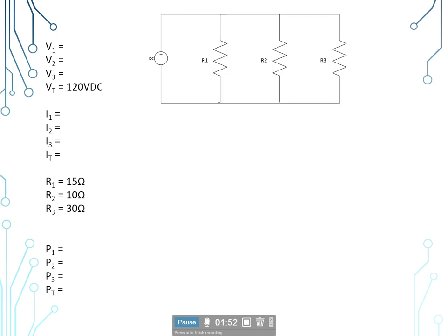Another method, we could use it here, but it's kind of counterproductive, is the product over sum. It's ideal if you only have 2 branches, because with that third branch, or each additional branch, you add calculations, room for error, margin for fat-fingering a key on the calculator.